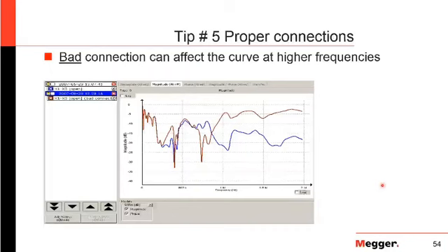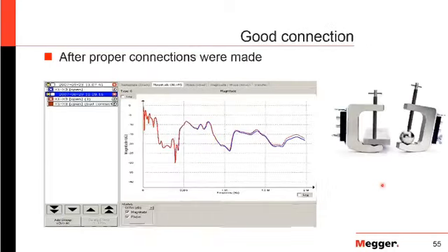to verify their connection. So continuing with connections, not only are you solidly connected to the terminal where you're injecting and measuring, you also need to ground off these devices. And so we isolate, because it's that coax cable, you want to isolate and ground off this connection as well. And the best thing to do is use what we call the shortest braided ground principle. So you have a braided ground that goes down, and then you have a little clip to make it adjustable. So if I have a really long bushing and I have a bunch of extra grounding, I just clip off to the part I want, and I make it kind of taut to the closest ground connection I can go to.